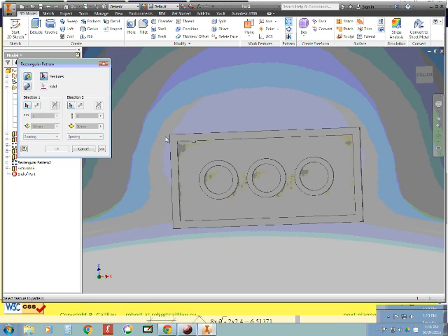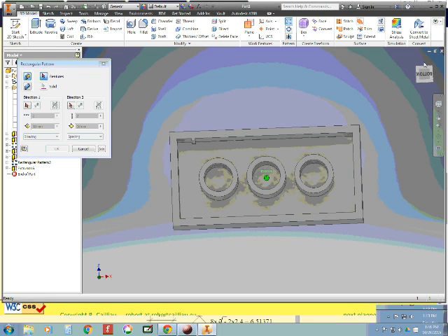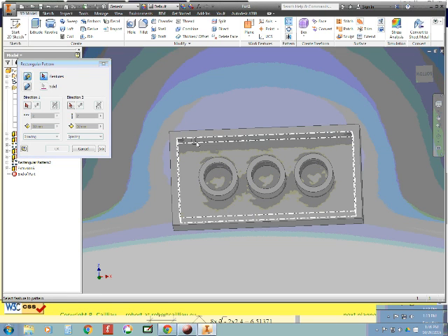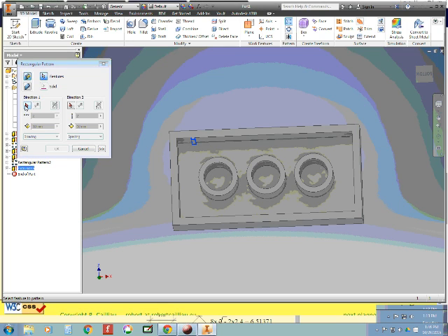Rectangular. And rotate that a little bit so I can see this feature. So that, again, choose the direction. And we want 8 millimeters between them, and we want 4. We want to choose another direction because we want to go across here. And I think if I choose this inside, yeah, this will probably work better. Flip the direction. Make sure you choose the inside.